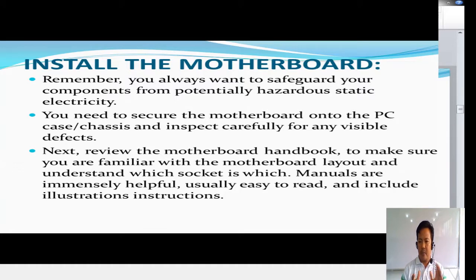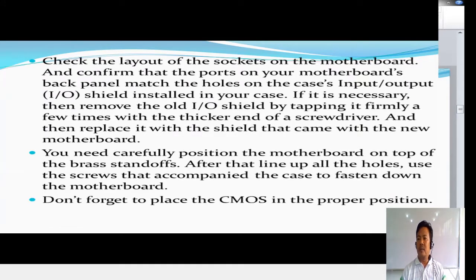So of course, before doing the disassembling and assembling, you have to be familiar with the motherboard that you're working with, or else there might be a problem during the installation process. So check the layout of the socket on the motherboard and confirm that the ports on your motherboard's back panel match to the holes in the input-output shield installed in your case. So you need to check the sockets of the board.